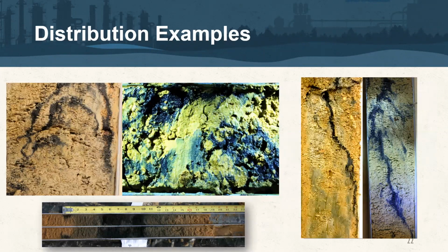Same thing on this slide here, just some distribution examples of a darker slurry and carrier fluid within the formation. I would call out that bottom left, that horizontal picture of the core. That's a silty sand mixture. And the reason I include that is when I talk about the injection design spacing and the flow rates and pressures that are required of this slurry or slurries like Fluoro-Sorb, the coarser the material, the easier it is to bleed off that energy. So contrary to popular belief, when we get into coarser grain materials, we're ramping up the pressures and flow rates, trying to create that fluidization and distribution. As you can see in that picture, it's very easy for that coarser material to bleed off energy out of that injection aperture window if you don't.